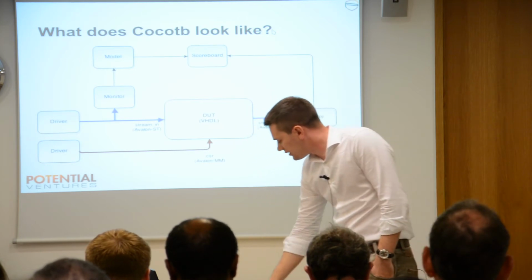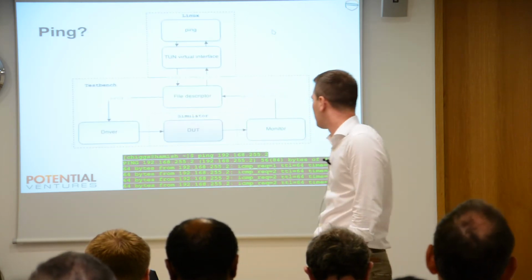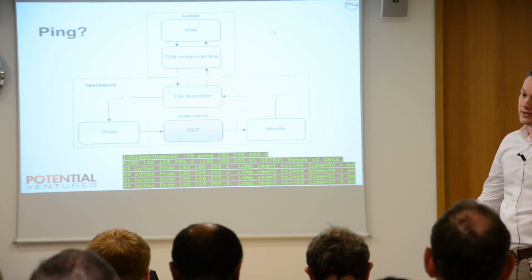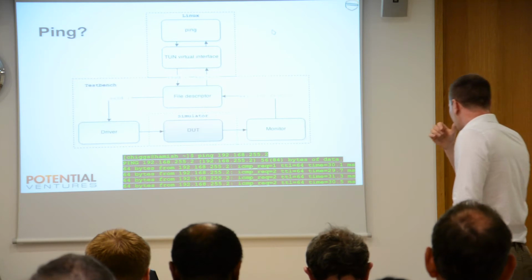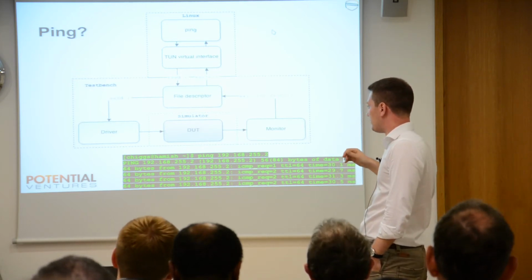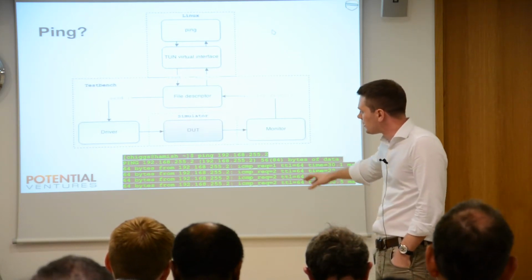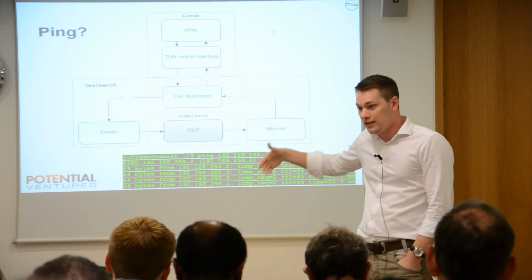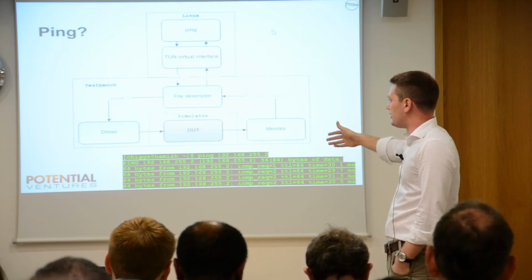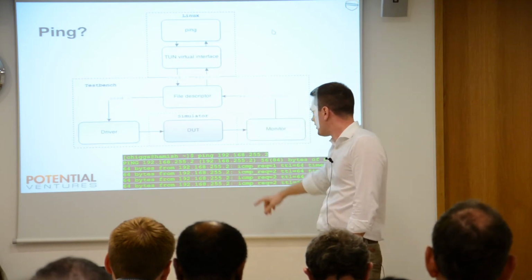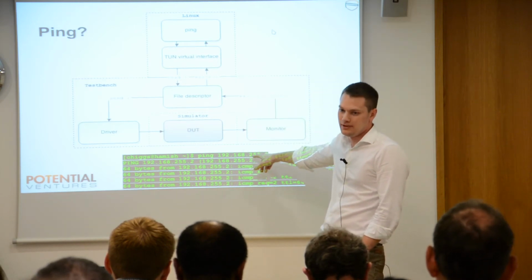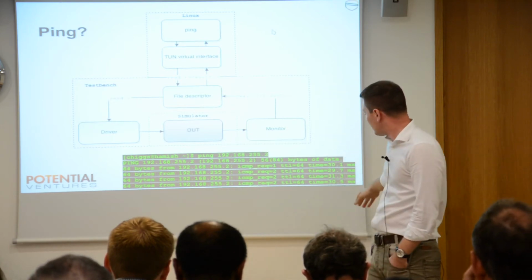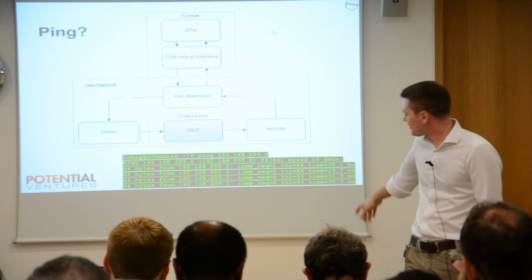The other thing that's quite handy, being Python, is that we can create quite complex test benches that interact, for example, with Linux. This is a tutorial that's in our documentation. Basically, we've got a simple design that responds to pings. We create a test bench that uses the Linux TUN/TAP virtual interface so that we can run ping in our terminal, and we ping our simulated piece of hardware. And we get not too bad response times. That's quicker than crossing the Atlantic.